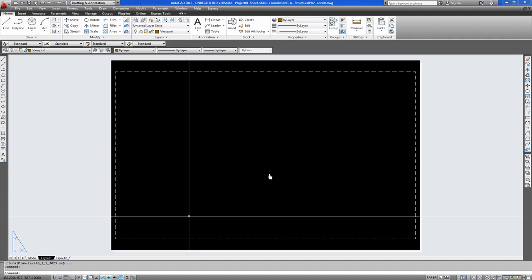Now we have, like I mentioned earlier, zoomed this to scale at 1:1. So this is what you need to be set at. You don't want any custom scales at this. In this case, it needs to be at 1:1. Fit to page is always unchecked when you are printing to scale, because fit to page would manipulate the size of your model.